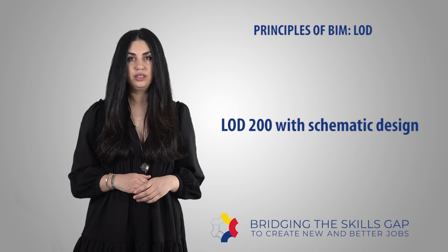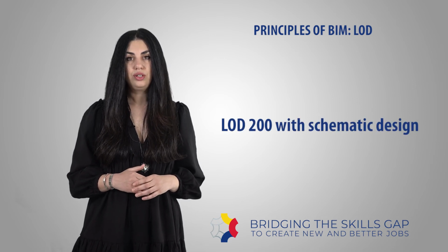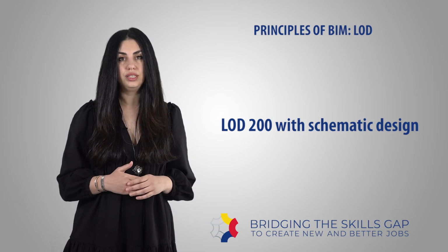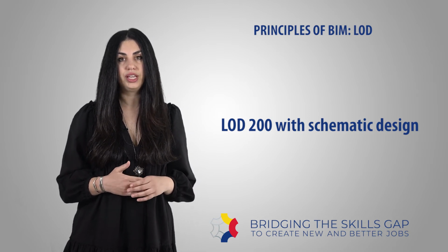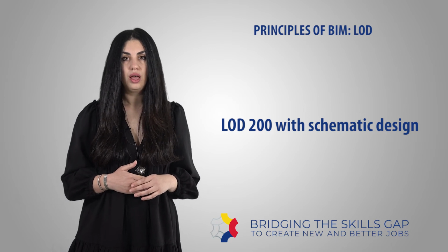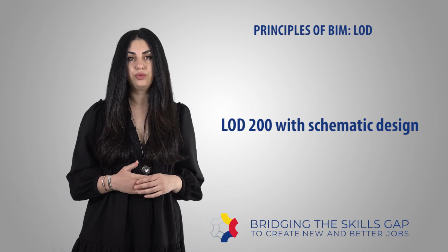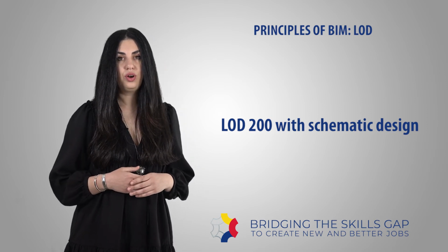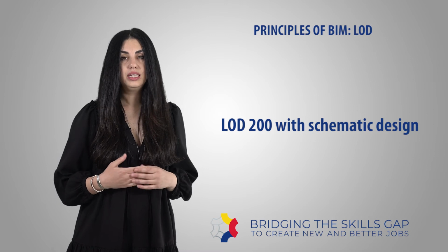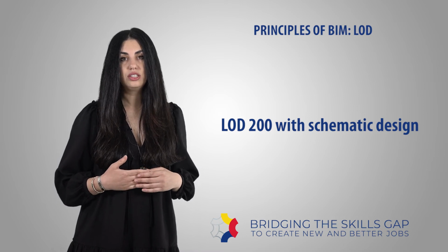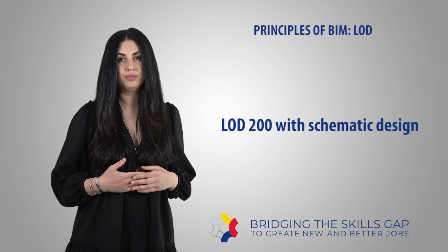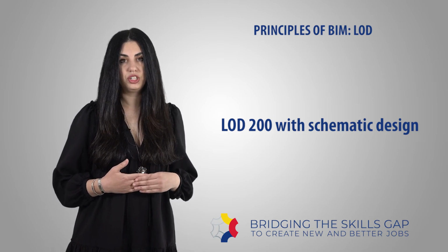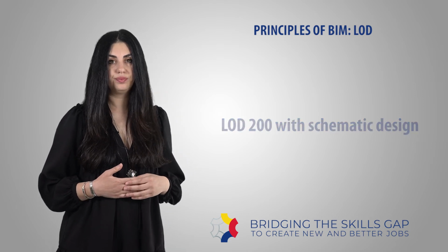LOD 200, schematic design, a general model where elements are modeled with approximate quantities: size, shape, location, and orientation. We can also attach non-geometric information to the model elements. With LOD 200, as you can see, this column that we have starts to take a shape of a steel column. This level needs to represent approximate dimensions, shape, and location.